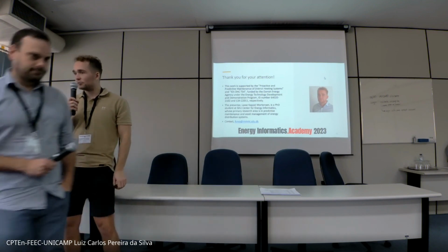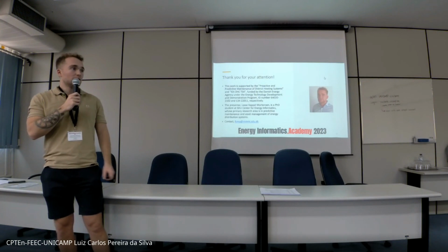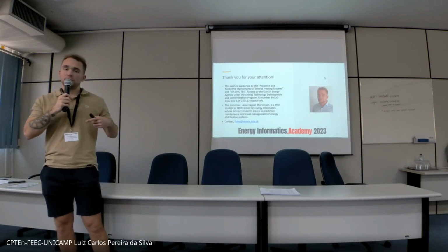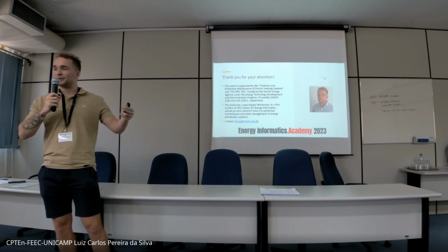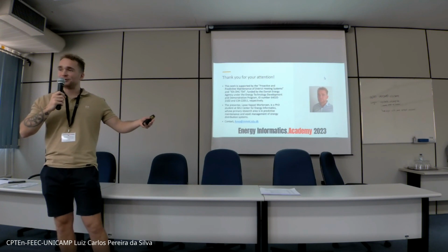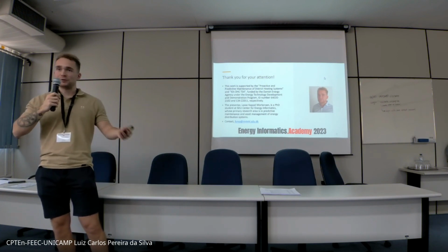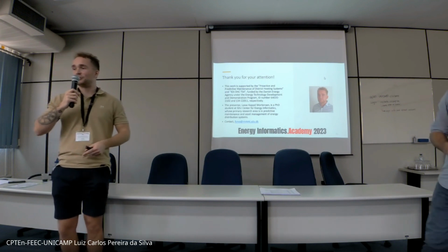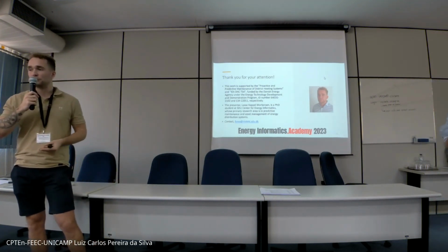Maybe one final note as well. New district heating pipes are being installed with copper wires to do leak tests, as a kind of reimbursement case if the district heating pipes fail after only 5 years or so. Maybe it has something to do with the installation, and the district heating company won't have to pay for that. You use copper wires and some resistance testing to catch those cases. But I don't have any data for how often those occur.